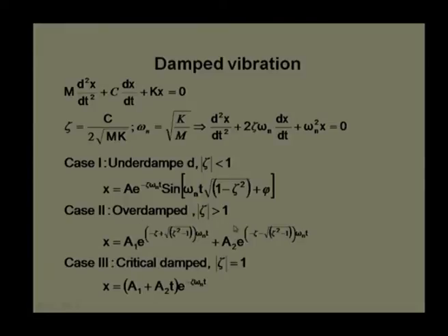While in the case of the overdamped system, it does not show that it will be damped immediately without taking much time; it may take slightly longer, or the magnitudes may take slightly longer, depending on the overall characteristics. While the first case clearly shows there is a sinusoidal term, a periodic term, that means it will keep going, with some oscillation but at lesser and lesser magnitude. There will be a reduction in amplitude of the initial disturbance, but it will continue over a number of cycles.